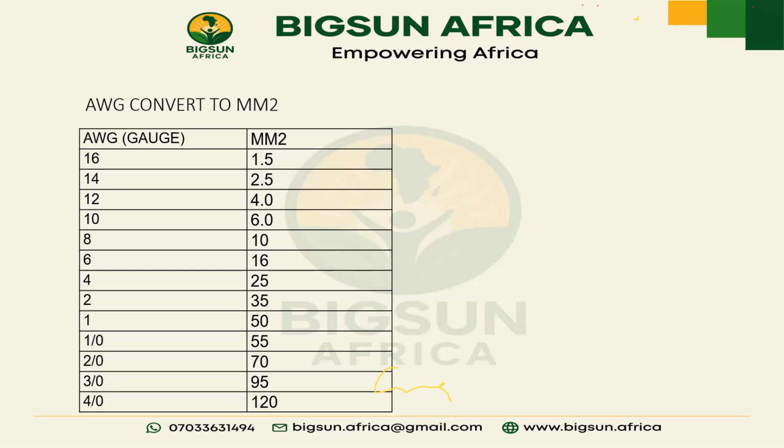So when you calculate your voltage drop index and get 3 or whatever value, you convert it to AWG, and from AWG we know the mm size in our local measure, because we are not in America.